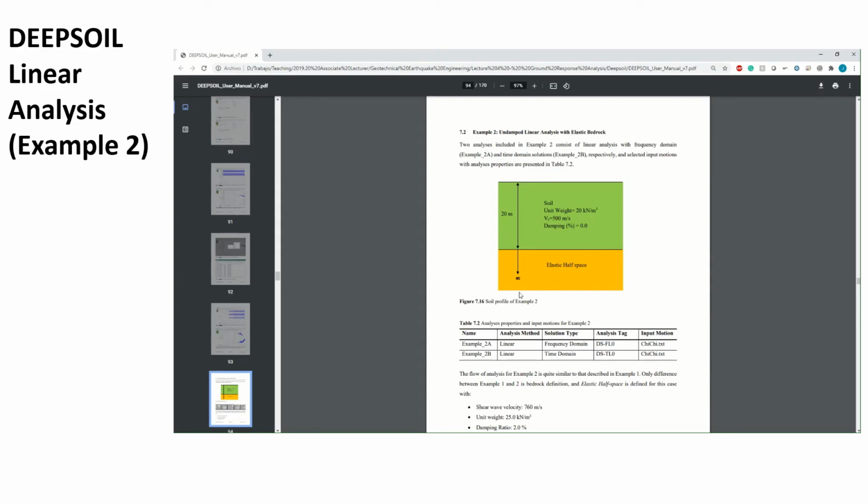So there will be part of energy dissipation as a consequence of that, which is known as another type of damping, radiation damping. So in essence, what we will have to see afterwards is that instead of having such a dramatic increase of the acceleration at the top of the soil surface, there should be a reduction in the maximum acceleration, velocity, and displacement with this option.